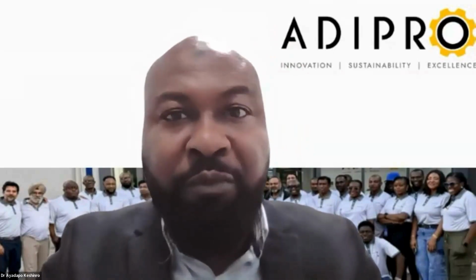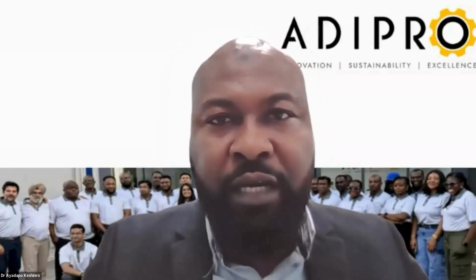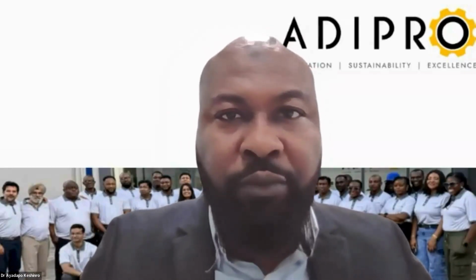So in our package we will typically have a little bit of moly. Molybdenum disulfide is very good for improving the anti-wear and anti-friction properties of the oil. You find a lot of PCMO packages not having moly in them, except they are now developing it for four-stroke engines. But in our case, we had to add the moly to improve the anti-wear properties of the oil.